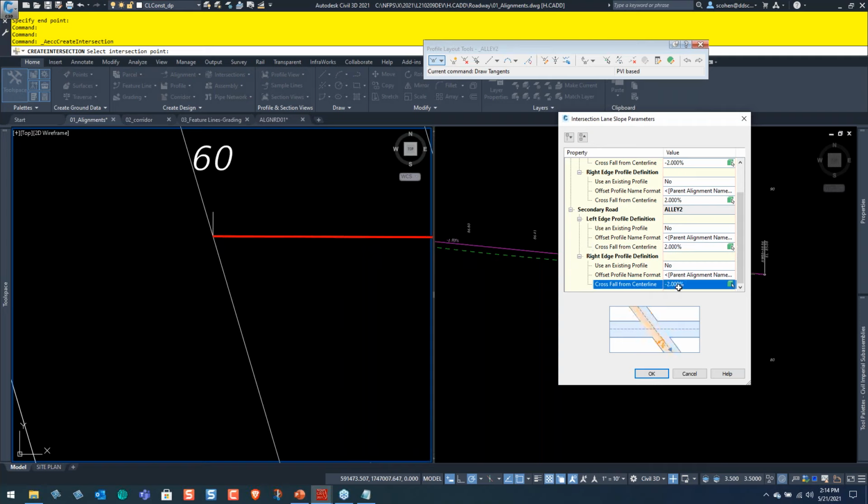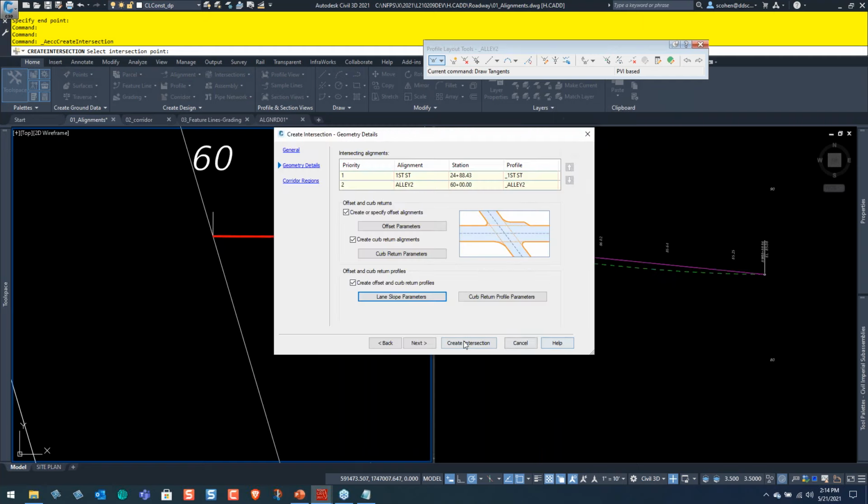We're keeping one side, getting the water to drain on one side. That way I don't have to have drainage in the middle. I can put my drainage towards the sides, and we don't have to reinforce. We can obviously set the type 9 structure into the curb, et cetera. That way it's outside the pavement, so we don't have to reinforce it.